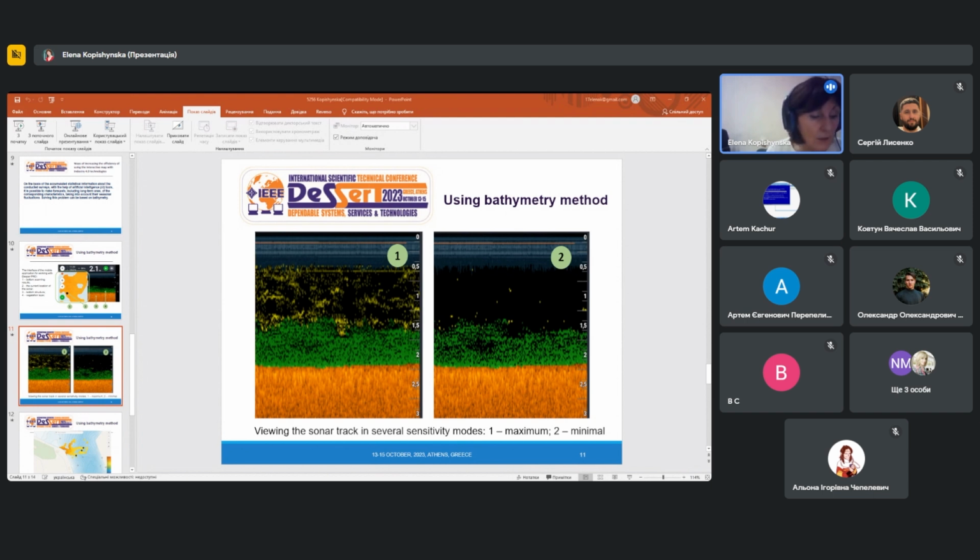As a result, to track the dynamics of increasing or decreasing depths, you need to move the sonar smoothly. It is possible to obtain a more accurate image of relief change and avoid blind areas during scanning by changing the signal frequency narrow beam mode to 190 kHz.